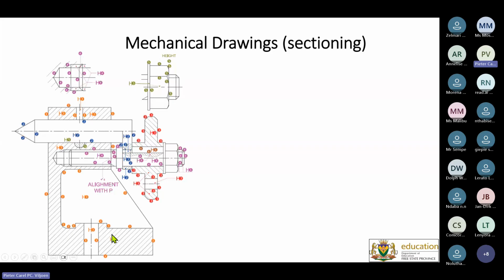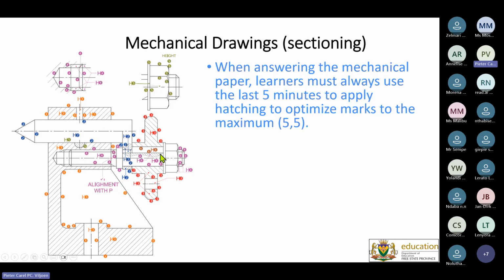Hatching is important. Now, this is an assembly drawing, but nothing prevents me from putting a round cylindrical object here somewhere. And remember that cylindrical objects like pins, shafts, bolts and studs are not hatched. This area over here is cylindrical, yes, but it is hollow. So that's where the thread is. So therefore, there's no hatching over there. I'm not going to spend time on the hatching of threads in the grade 10 content because nuts and bolts are not involved with grade 10s.